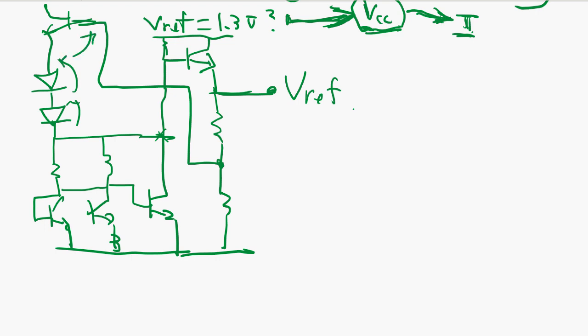You stack up 3 times, and the output feedback goes to this ratio. Okay, so you analyze this circuit, you can get a 4 VBE higher constant voltage. It's compensated against the VCC.